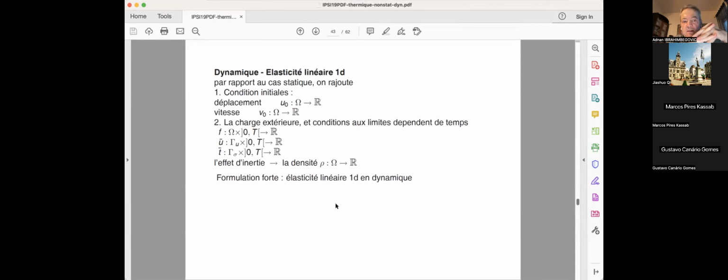So this time around, instead of saying that displacement is only a function of x, the space coordinate, you have to say that displacement is also a function of t, and the loading is, of course, a function of t, or if it's distributed, is a function of both x and t. Imposed displacement is a function of t. One case of imposed displacement is an earthquake: for your structure, the base support starts moving because of the earthquake, and then you have to take into account what happens. Or applied traction could also be time dependent, and so on and so forth.